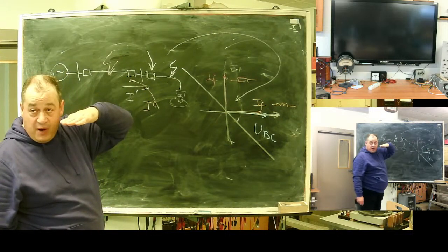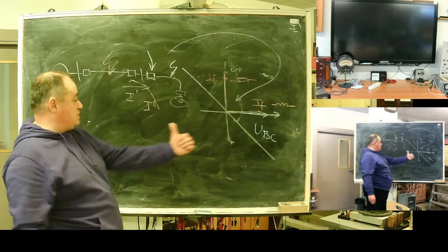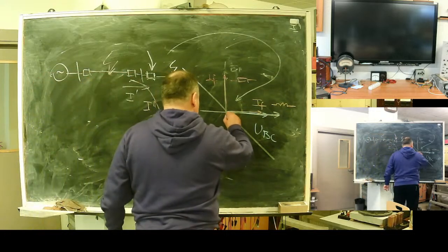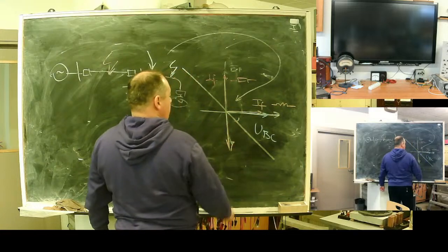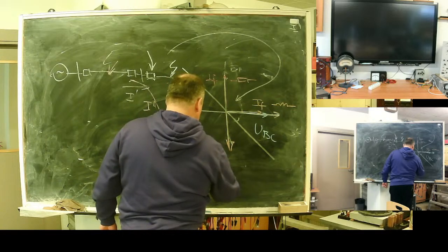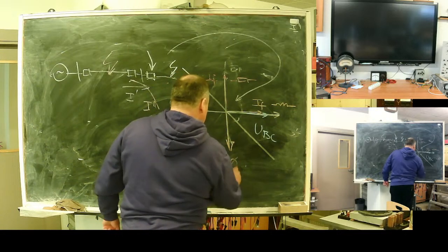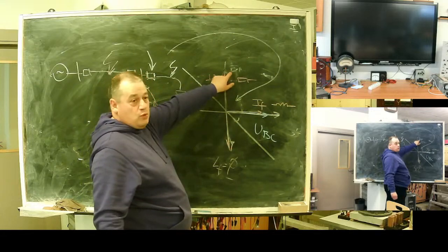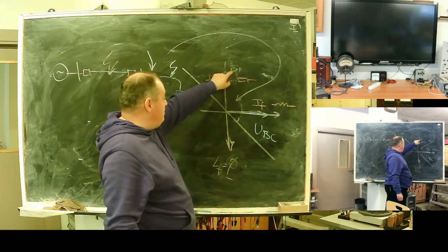Angle 0 but with a minus sign, because current inflows, meaning it will be somewhere here. In case X fault is 0, it will go in opposition to A phase EMF.